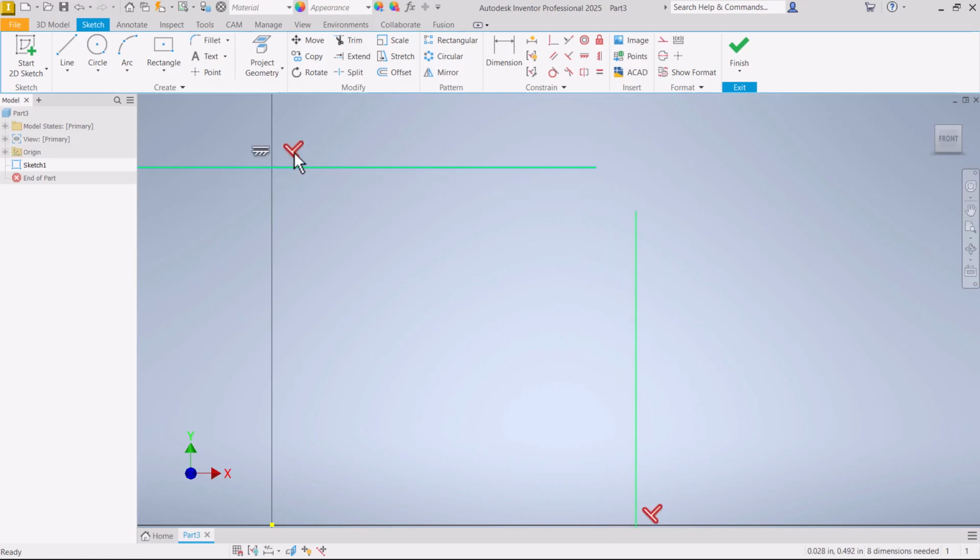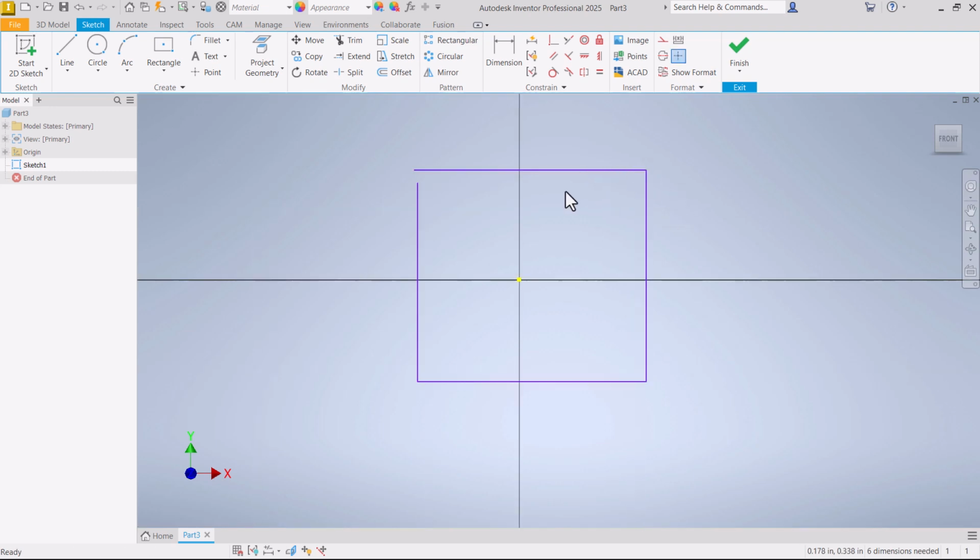You can see here the perpendicular constraint, this line and this line, they are a pair that tell these two lines are perpendicular to each other. But when we are using coincident, they are in the same place, so we see them right there side by side. Deleting one deletes the other. So that's the first thing you need to recognize, is that coincident constraints are created all the time as you draw, and you don't have to apply all of them manually yourself.